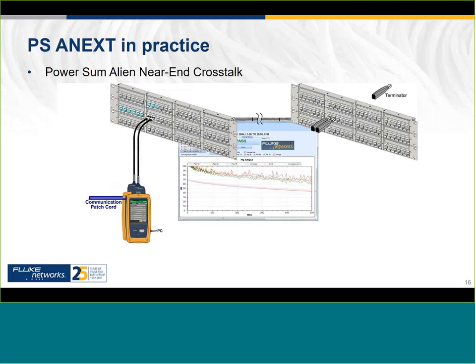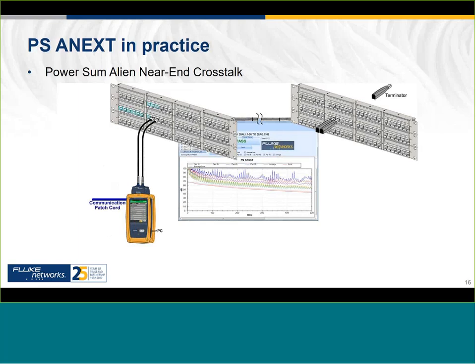As we get closer in, as you just saw there, the connectors at either side, they're the ones generating quite a lot of crosstalk. So the last three measurements are down the bottom. So if we move through here, that's all the cables in the bundle.